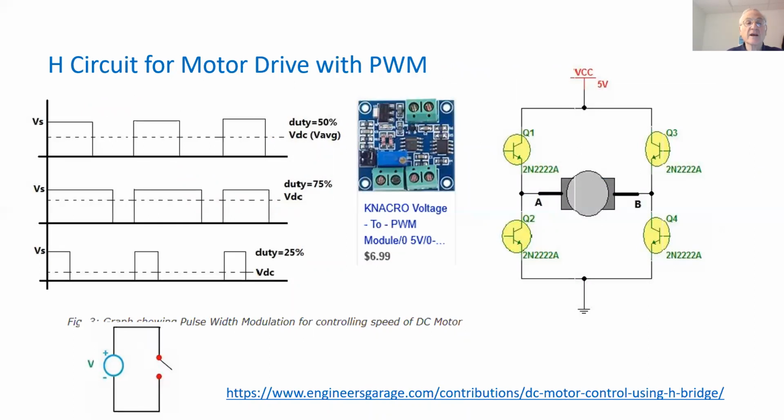We see over here pulse width modulation, a very common way of providing voltage through the driver to the motor. We have a pulse over here. Depending on how long we keep the pulse closed, we will generate the voltage, and the average of this is what drives the motor, the RMS. We can purchase a PWM circuit and connect it to our system. Most of the time it comes enclosed in a box with plug-and-play cables.